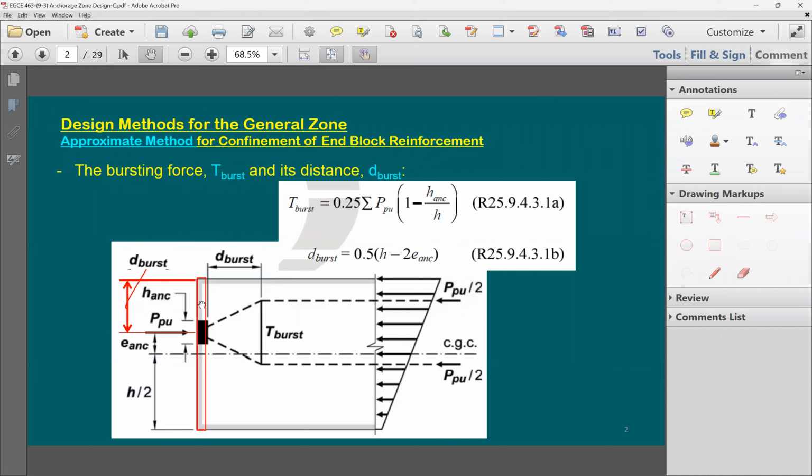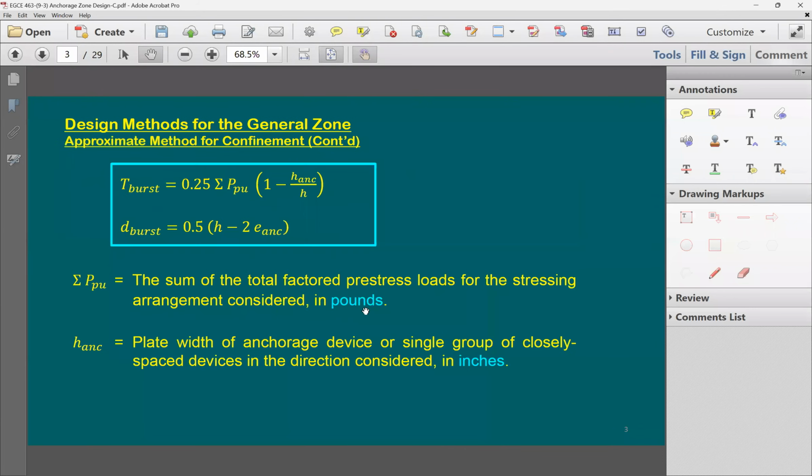Especially if you want to really eliminate all the tension forces, you need to go with a very thick plate to be sure that it's going to be a rigid plate, and the plate itself is not going to be deflecting or deforming, and provides completely uniform stresses on the end of the beam. So it's going to be a cost. The plate is going to be heavy. You don't want to do this.